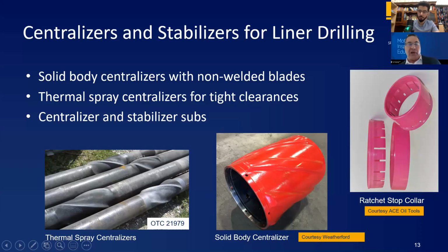So if you can visualize, you have your casing rotating inside the centralizer. We call this centralizer non-rotating with respect to the wellbore itself. And theoretically, it just slides with the pipe. So with this rubber lining, you have a lower coefficient of friction, which in itself reduces the torque. So when you're running the torque and drag models, you can see less torque versus a conventional one without the rubber here. So this is a very robust centralizer.